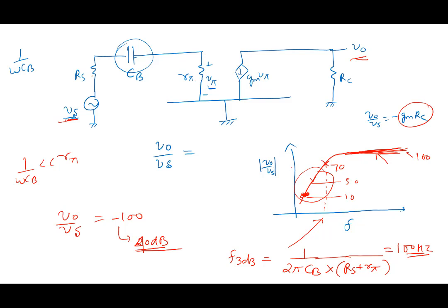The high frequency signal will see more amplification, the low frequency signal will see less amplification. So it will cause distortion of the whole thing. So you don't want to operate in this region here. You want to operate in this flat region here, where whatever the ratios of different frequencies in your input signal, the same ratios will come out if you operate it here. Okay? Alright, so this is there, fine.